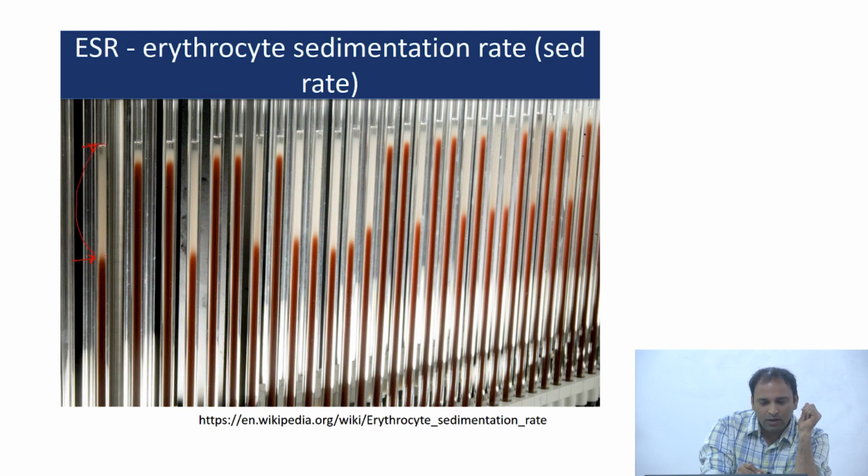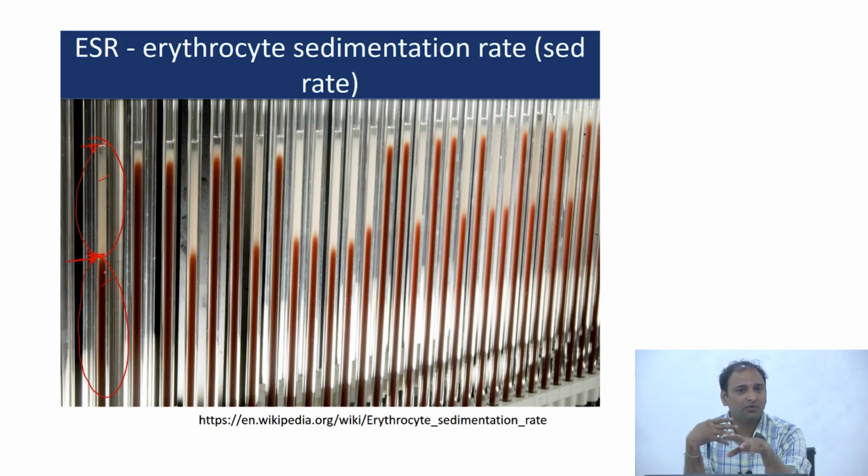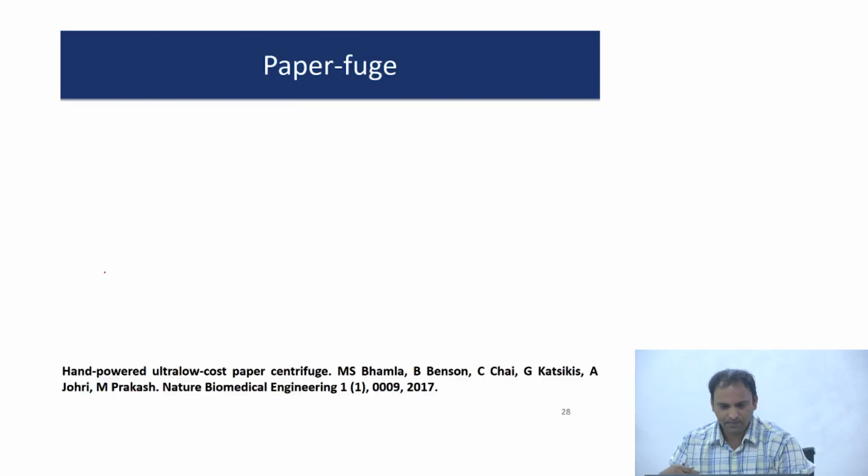Therefore this is clear plasma. There are no particles there, and all the particles are now concentrated here. So by measuring this interface between the clear fluid and the sample where there are blood particles, I can actually measure the sedimentation rates. This is what is typically done. And depending upon, as I said, disease conditions and the type of person you're dealing with, you'll have different values. So this is one application where you can use exactly the same equations that you used. If you know the dimensions of the blood particles and the viscosity of the blood, you can also calculate the settling rate.